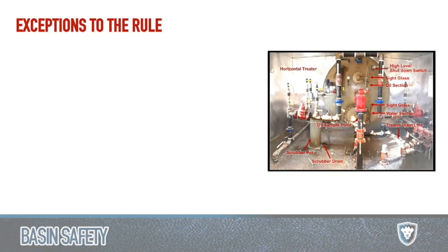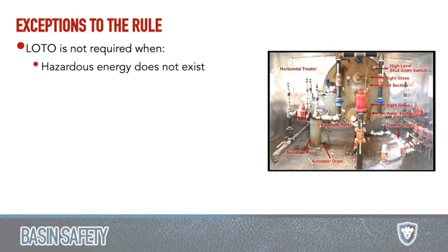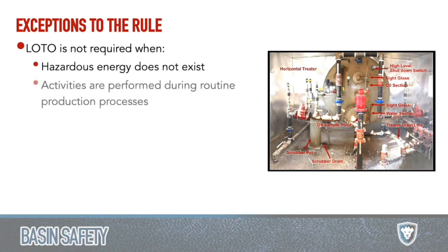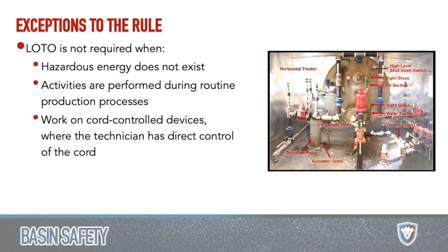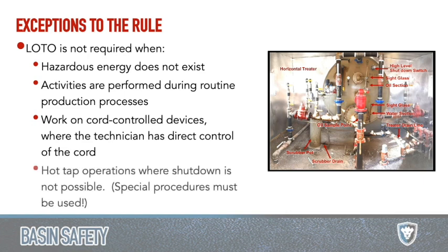So there are some exceptions to this rule. It's not required if hazardous energy does not exist. It's also not required if something is being performed during routine operations, for example, removing a filter sock in a saltwater disposal. Even though water coming through is a hazard, we close the valve, so that's a routine operation. Cord-controlled devices that can be unplugged, we don't need to worry about then. And also hot tap operations where shutdown is not possible, but there are additional procedures involved in that.